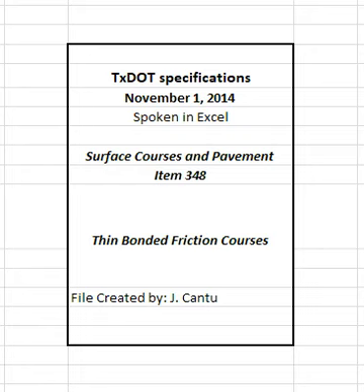Stockpile aggregates for each source and type separately. Determine aggregate gradations for mixture design and production testing based on the washed sieve analysis given in Tex 200F, Part 2. 2.1.1 Coarse aggregate. Coarse aggregate stockpiles must have no more than 20% material passing the number 8 sieve.